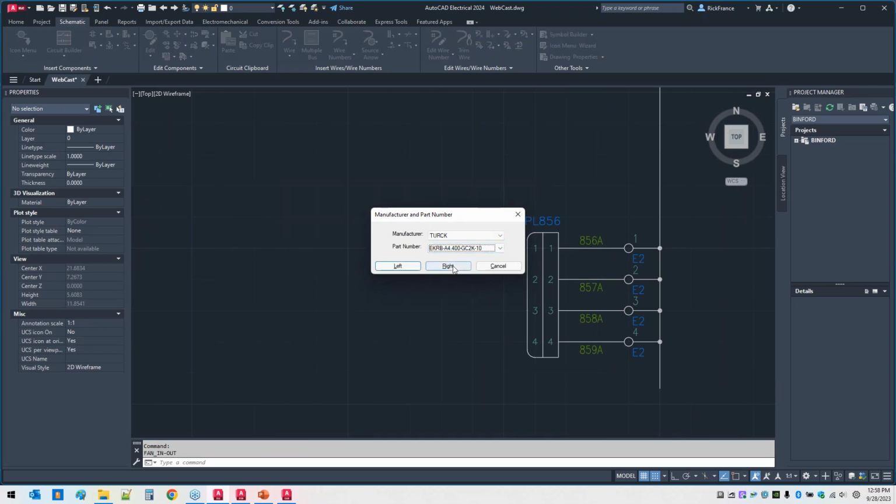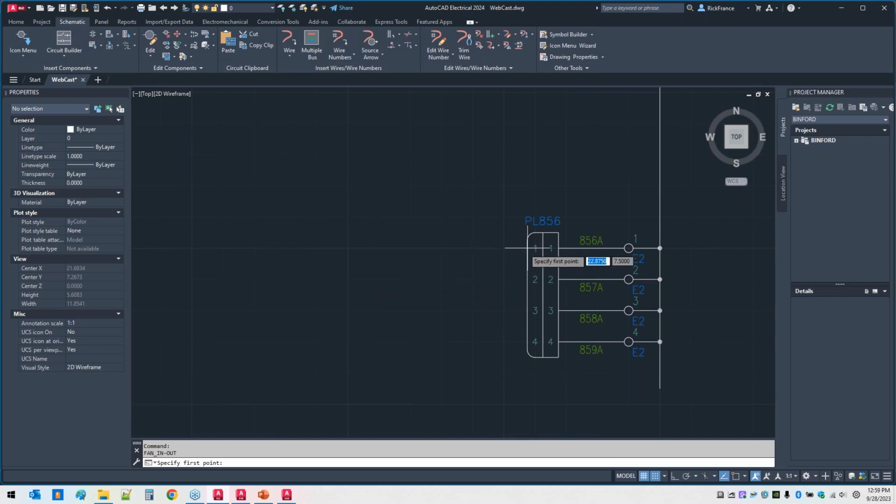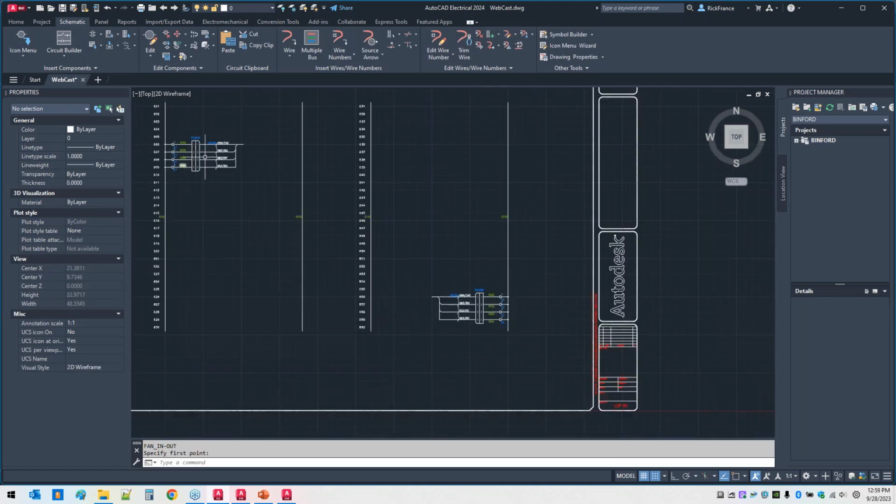And then likewise over here, I can do the exact same thing, same cable, and say on the right, because I'm working from right to left, and it will put in the exact same thing. In this case, the same cable. They're marked different now, but once I went into AutoCAD Electrical, added my source and destination arrows and linked everything up, it would understand this is the same cable, the same wire numbers, everything, and it would work.